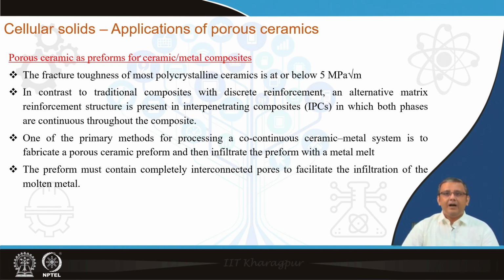So, a composite material where a combination of a ceramic and metal is used, in this way typically as metal matrix composites, where a metal contains a small amount of ceramic particles, like alumina, silicon carbide, silicon nitride, have been used very often for many applications in automobile, in aerospace and all such cases. But when these metal matrix composites are used with individual ceramic particles, the particle content is very much limited, up to around 10 volume percent or something like that, because if it goes beyond that, fabrication becomes pretty difficult.